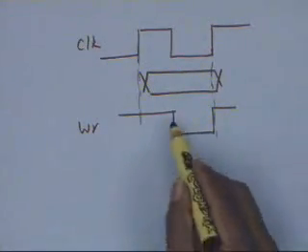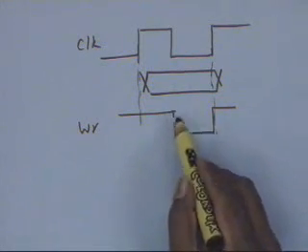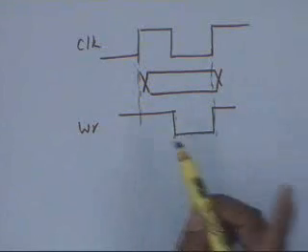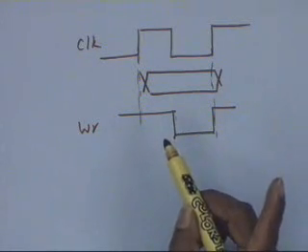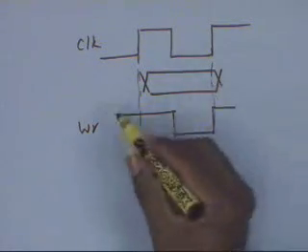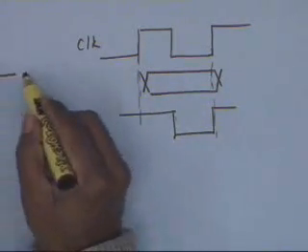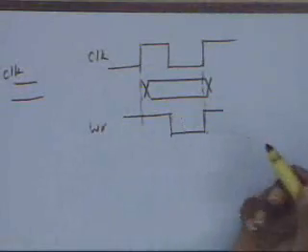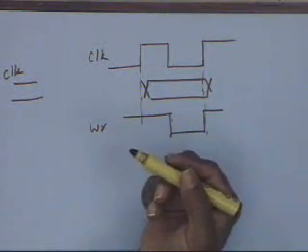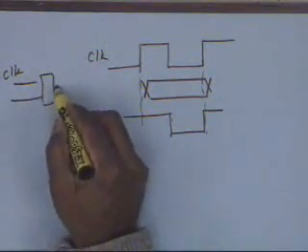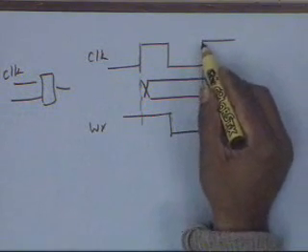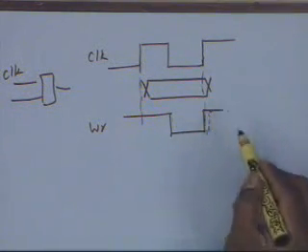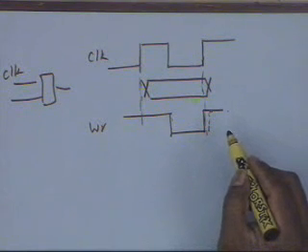I can do it in one clock cycle, so now it is not being associated with the state. If it is a Moore, it's the output of a state gated with the clock. Please remember this, because any type of gating, so if you are taking a clock as an input and putting some gate, whatever, an AND gate or OR gate or NOR gate, this particular edge will be delayed from this. So this particular edge will actually arrive here. And that's dangerous for the write.